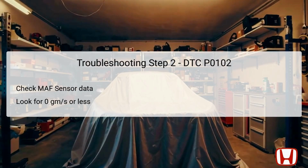In the second troubleshooting step, utilize the Honda Diagnostic System, HDS, to check the MAF sensor data from the data list. You are looking specifically for readings around 0 grams per second or 0.1 volts or less. If the MAF readings are within these limits, it indicates a significant issue needing immediate attention. If the readings are indeed at or below these specified values, proceed to the next step in the troubleshooting process. Conversely, if readings are normal, the issue may be intermittent, suggesting the system is functioning correctly at that time.